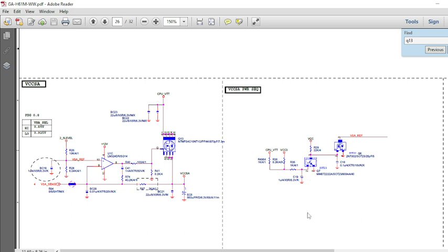One thing you can do is trace the VRM enable pin on the VRM IC. From that, keep the multimeter in buzzer mode and check which component is connected to that pin. This component will be beside our CPU socket, at the bottom left. There will be many transistors and MOSFETs over there. Just check which one gives a beep, and remove that. After removing that, your VCore enable will be available and your display will also be available.